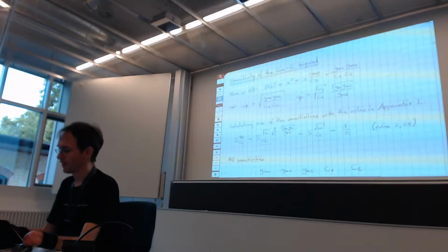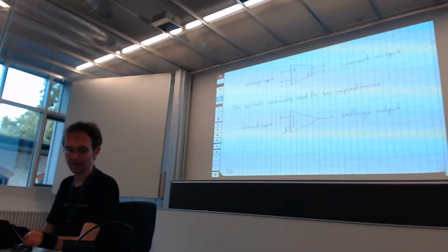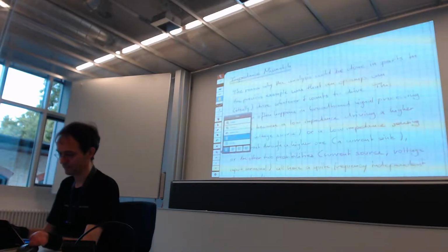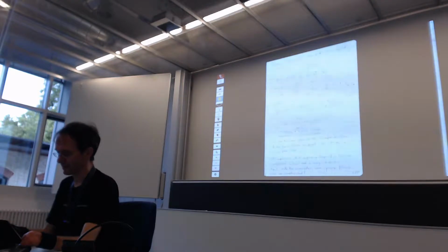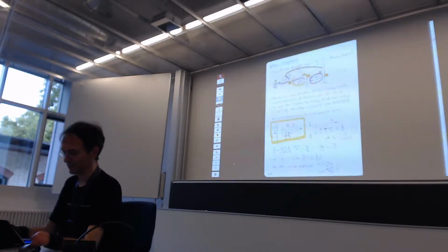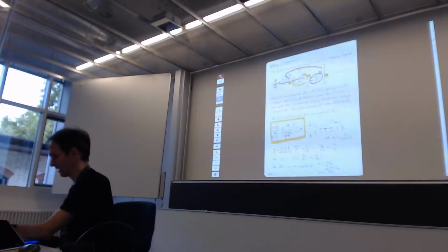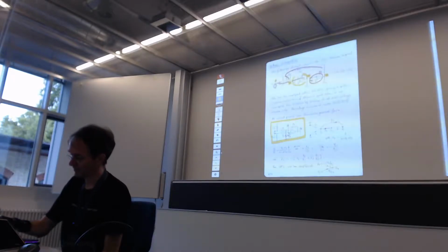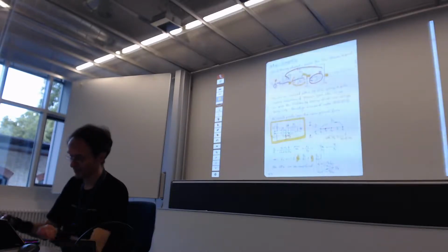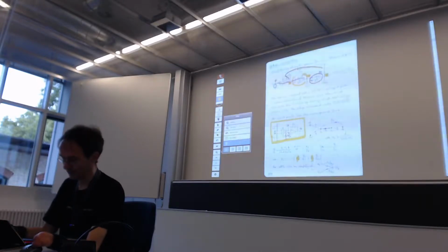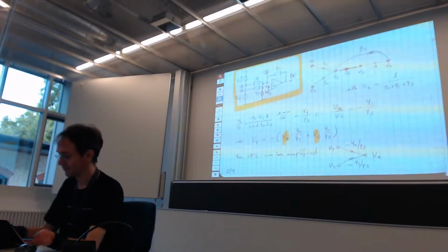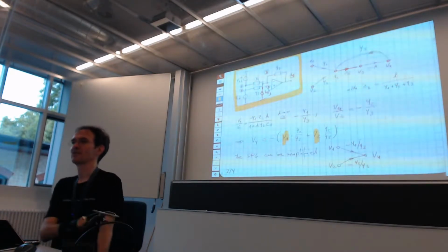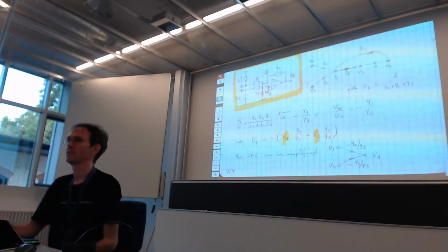When I showed you how to combine signal transfer functions, I have to zoom out. If you compare the signal transfer functions, this we did down here, the correct solution for signal transfer functions is, of course, that if you have two signals at the input here, then you simply add the influence of both signals. This is what it means to be a linear circuit, isn't it? So input 1 times transfer function 1 plus input 2 times transfer function 2.